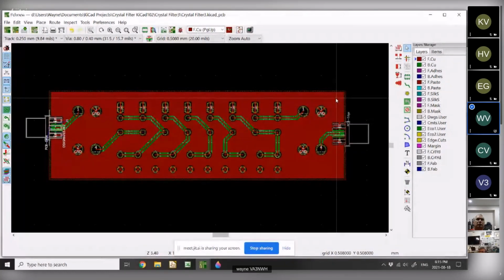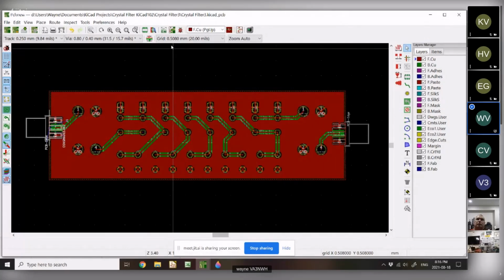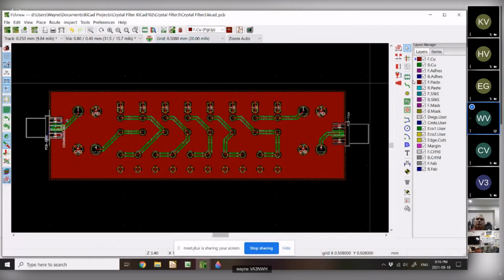I don't remember. I'll look it up. I think you use a pin header hole. So you take a single pin header, and that gives you the hole that you probably want. And then you can take the hole, or if that's not big enough, you can make the hole any size you want. I shouldn't have said pin header. That's wrong. Pin headers are too small. What I did one time was I used a pin header, then I enlarged the hole to the size I wanted. Then I found later that they actually have holes in the footprints list, if you want to use them. Okay.